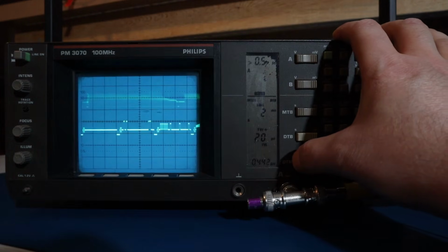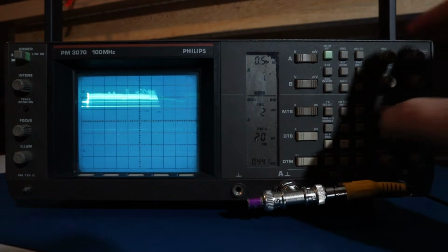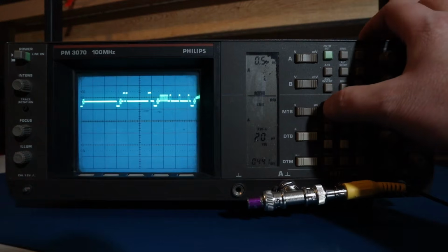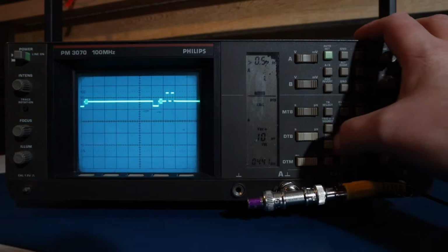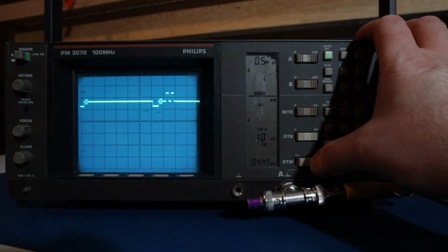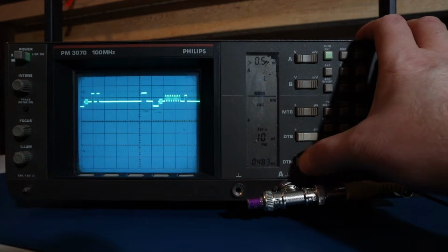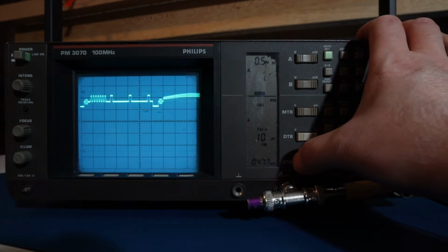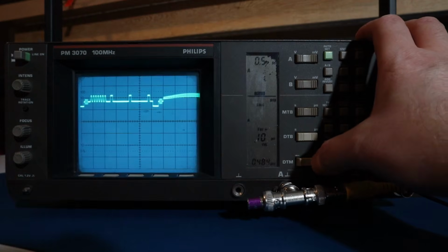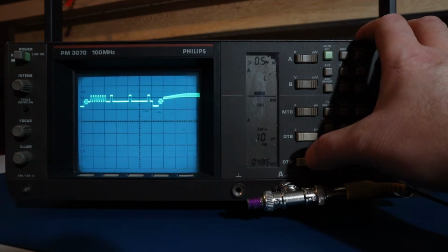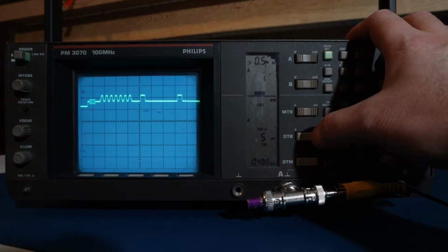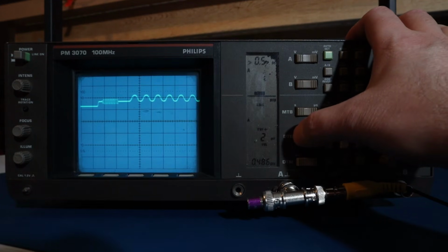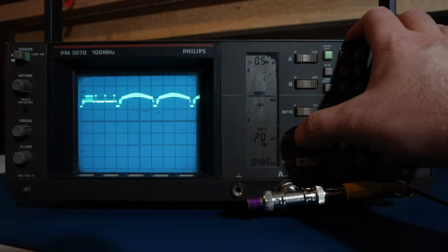And when we get to the interesting lines of 20 and 21, I'll just remove the display of the signal from the main time base. Perfect! There are our lines of interest. We can play around and zoom into this and stuff. And that's how we can look at the different lines on an old analog scope.